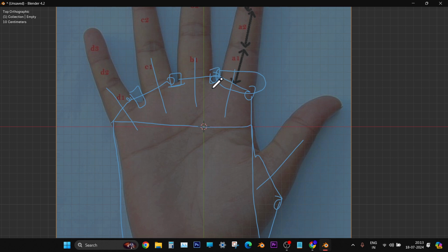For those gaps, now we'll have edges and all, because from there the edges will start and then you will continue till the palm. So those things also need a knife. So in that case, we'll be adding using the knife tool, and then we'll start extruding. Like that, we'll be doing. Yeah. So let's go to the modeling now.